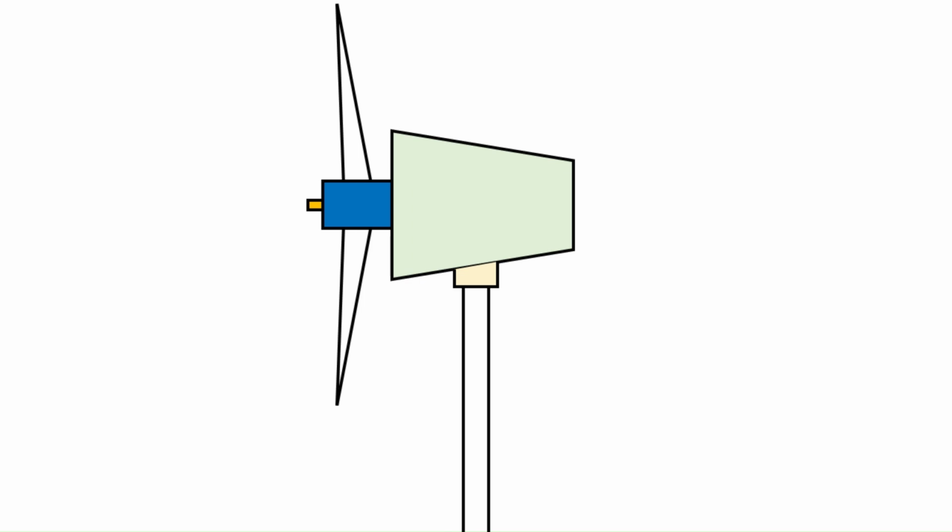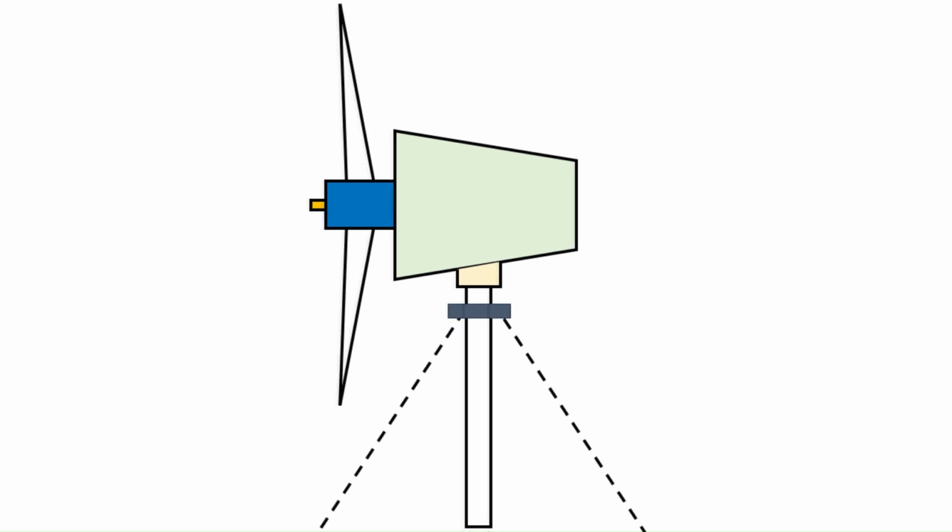These towers are fabricated by joining tubular sections of 10 to 20 meter length. The complete tower is assembled at the site within 2 to 3 days. These towers are comparatively good looking and less danger to the avian population. For small systems, tower with guyed steel poles is used. By partially supporting the turbine on guy wire, cost of the tower can be considerably reduced. Usually, 4 cables equally spaced and inclined at 45 degrees support the tower.